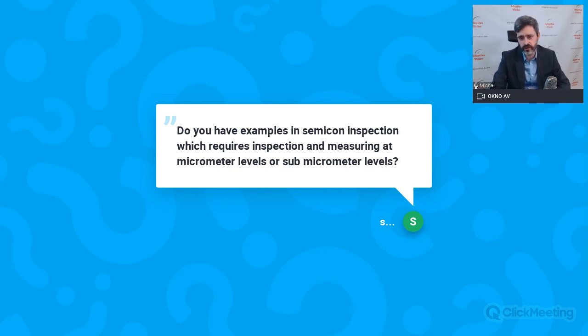So you should consider lighting, you should consider optics, you should consider resolution of your camera, not only software. Software is just the last element. And the general rule in software is that if information is not on the image, we will not extract it. So if there is noise and there is not enough resolution, we cannot go to very high precision measurements, because software is no magic. It can only extract information which is there already.